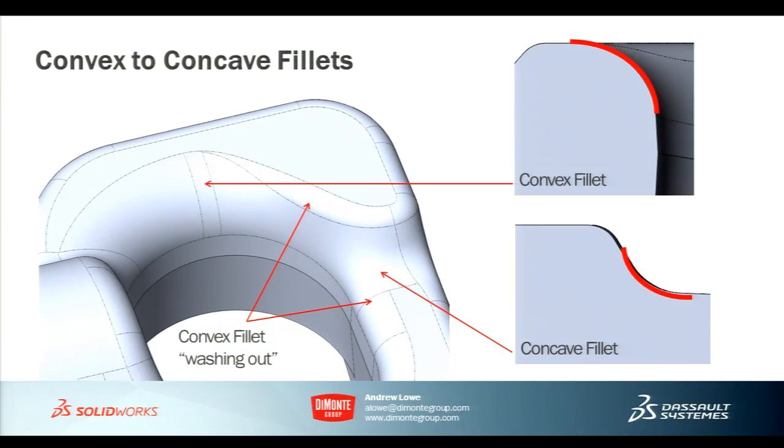And this is a part I remodeled. It was inspired by a customer's part, and it was something that was originally designed in either the 30s or 40s entirely on paper, where it must have been nice for the draftsman to specify a fillet there, another fillet there, and have someone else figure out how all these fillets are going to flow into each other. But in the days of CAD, we need to explicitly define what our models look like, so we're going to look at a technique we can use to get this face into the model and to blend the convex fillet into the concave fillet.